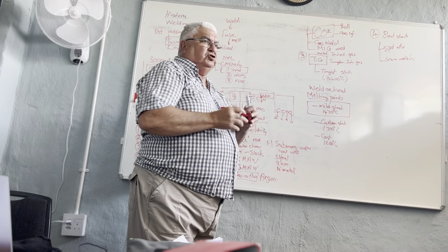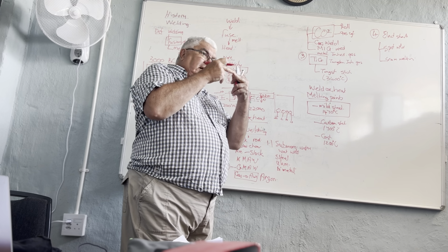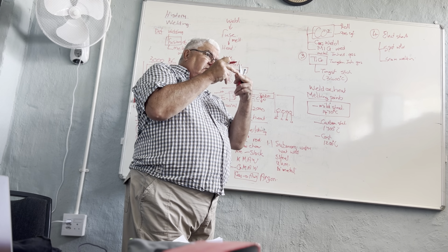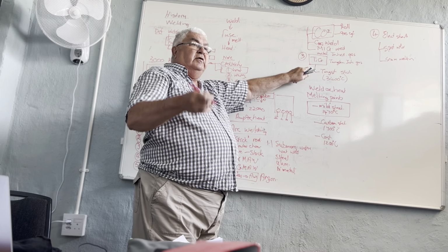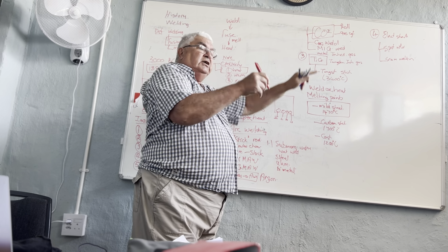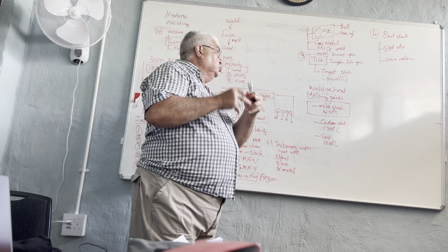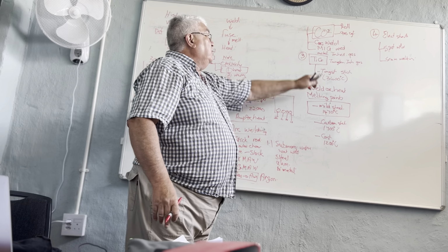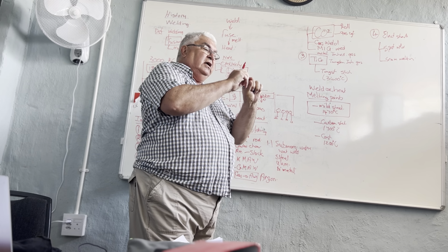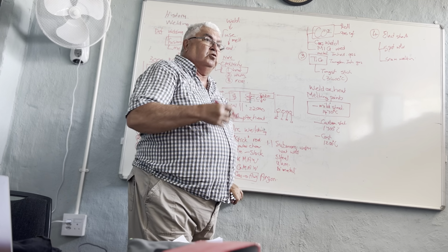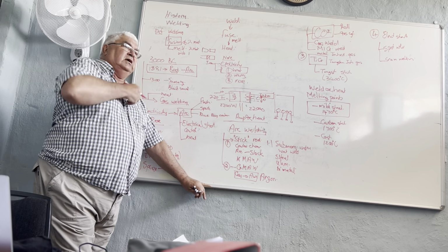Spot welding doesn't use a machine, it does use the same transformer principle, but there are two copper electrodes pressing on material, creating the short, and there's no filler material. This one has got a filler material, this one has got a filler material, that one has got a filler material. Filler material meaning there's a rod or some material that you can fill up. Spot welding, you put the two plates together, thin material, it melts that spot and it melts the two together into one. Seam welding is where you've got that electrical process like seaming. So sometimes you get material that looks like it's been seamed together. That's called seam welding. Many tins, many holders are seam welded. So that means you've got that seam that's welded.